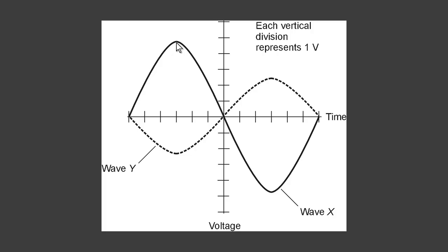So now we're only concerned with the peak-to-peak voltage of the composite. Well, here is where the positive peak of the composite will take place, and it will be about plus 4.9 volts plus a negative 2.2 volts. Now I'm interpolating a little bit here. I'm guesstimating, because these values are not clearly labeled on the diagram, we kind of have to guess. But 4.9 minus 2.2 is going to give us plus 2.7 volts peak here.